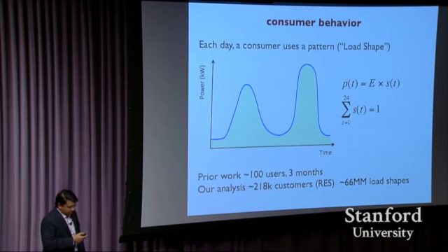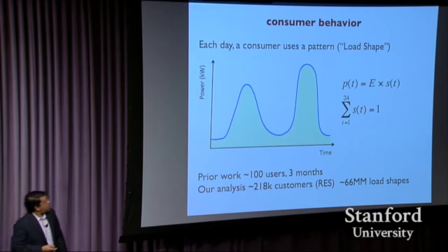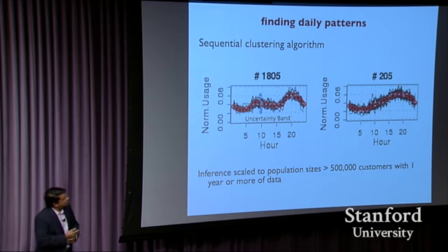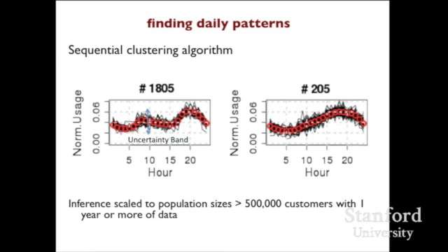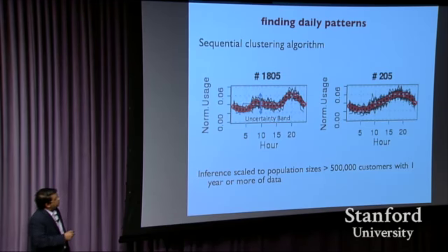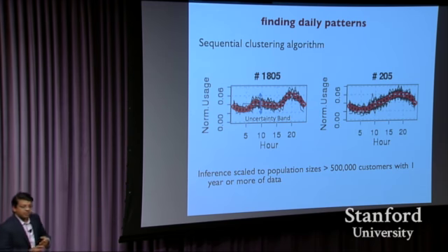And in fact, we can verify that statistically after we count the number of load shapes that there are. So what we did is we took these normalized shapes and we ran a special clustering algorithm that we built so it could run on a database that had about 66 million residential load shapes. And what this algorithm does is pretty simple. It tries to find a certain number of cluster centers so that every cluster only allows a finite and controlled deviation from the cluster center. So we specified that as a parameter. Okay, typically we found 20% is a good number. So that is about 1% error from the cluster center per hour.